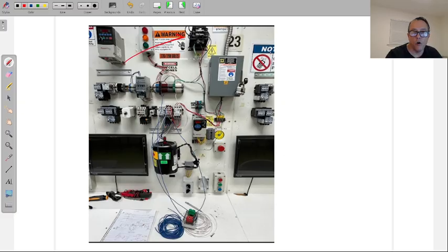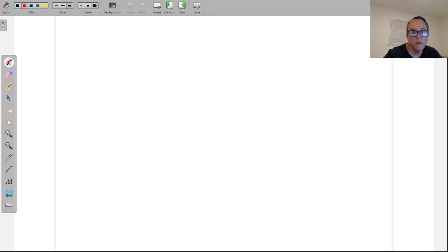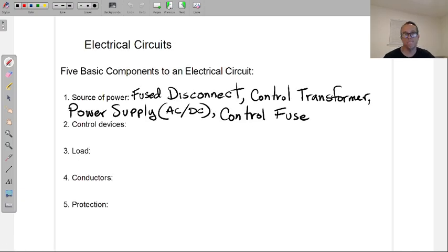All right, not all transformers have those fuses available, but we are using them there. So I'm not going to put them here. Controlled transformer may or may not have fuses, so I don't want to go that far into understanding the power source. But this is it. Other than some panel somewhere bringing power to the fuse disconnect. But that panel is probably sending power to other things and technically not part of the motor control circuit.